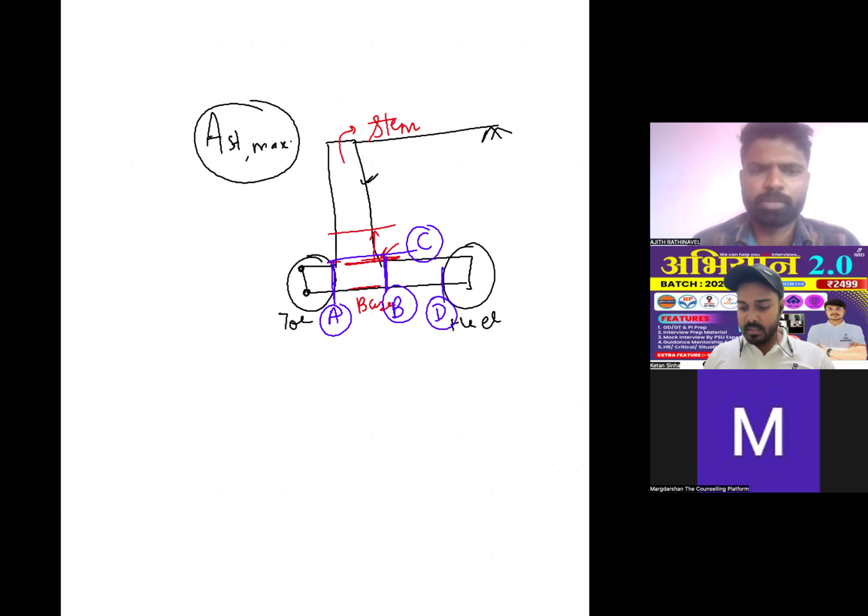Why? What does a shear key do? It gives stability against sliding, sir. How? By providing the shear key, there will be an additional passive earth pressure that will act on the shear key, sir. So it will resist the sliding. Okay, fine.